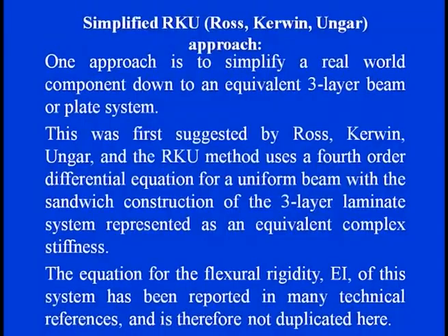In that, the basic impact comes on the flexural rigidity EI, because sometimes we cannot simply replace this EI, where E is the Young's modulus and I is the cross sectional feature. So both material and cross sectional features for the equivalence of the 3-layer laminated part are somewhat more complex, because when you go in a uniform way, it is pretty easy to put it in a linear algebraic way, just adding those parts E1, E2, E3, or I1, I2, I3, and we can get it. No, it is not like that, because the real world problems are somewhat different.